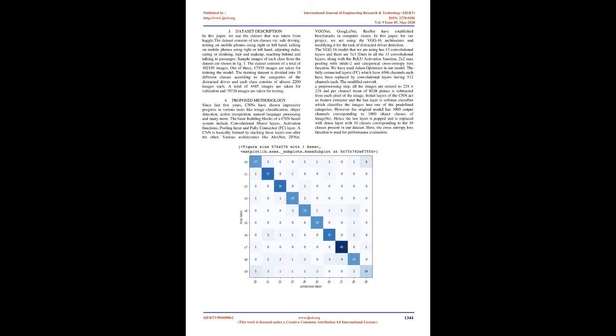The different vehicular-based techniques used were lane detection, eye blinking period, steering wheel angle, and steering wheel behavior. A single angle sensor was placed under the steering of the car, used for detecting the driver's steering behaviors. The physiological parameters-based techniques detected drowsiness based on drivers' physical conditions such as heart rate, pulse rate, breathing rate, respiratory rate, and body temperature, etc. These biological parameters are more reliable and accurate in drowsiness detection as they are concerned with what is happening with the driver physically.